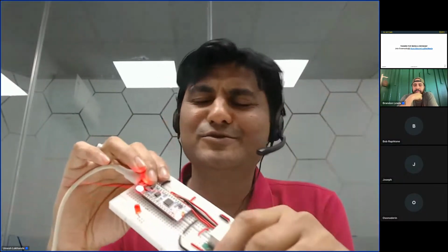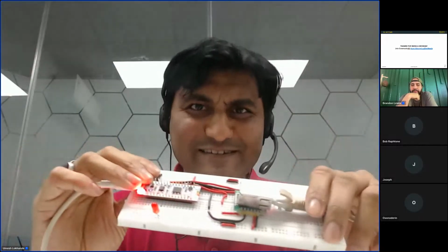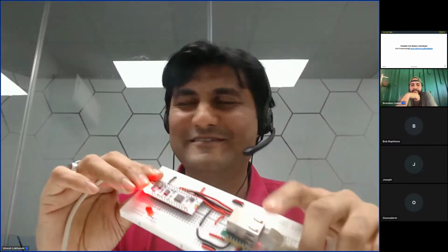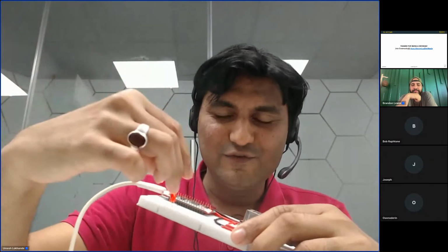And in industry, when you have multiple Modbus servers, the funny part, which is not a part of this, maybe someday in the future we will talk about how sensors are made. The companies make sensors. They use Modbus and a microcontroller, connect the physics into the chip, and integrate the logic to act as a Modbus server. So you can integrate it very easily, because that Modbus sensor could continuously broadcast the data.